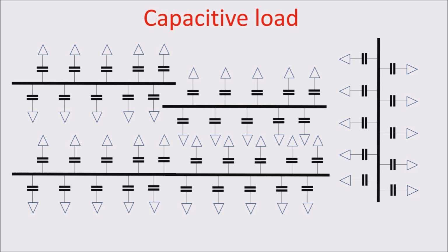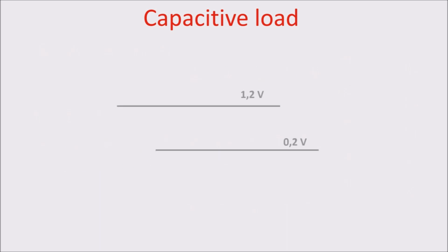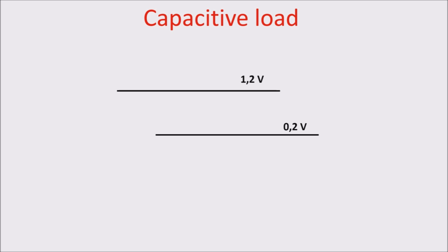We have a lot of them because every time we have a different voltage level between 2 points, we have a capacitance effect between these 2 points. Calculating the equivalent capacitance is not easy, but it can be done with the help of simulators. Anyway, the designer has to keep low this equivalent total capacitance, especially the parasitic ones, which is responsible for power dissipation, even when the MOSFET is not working, so when it is not switching.